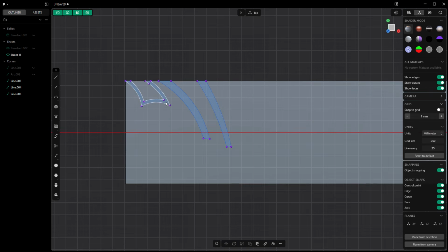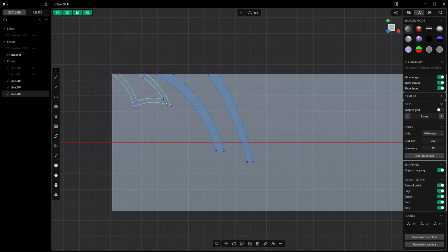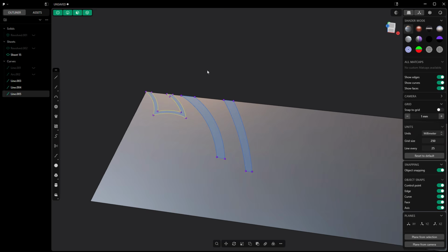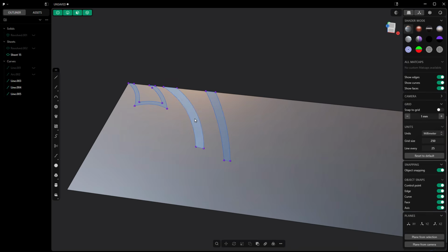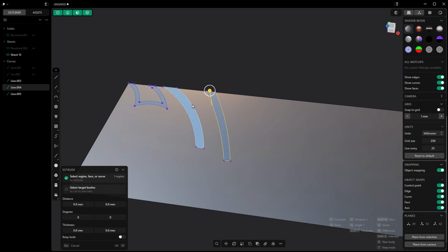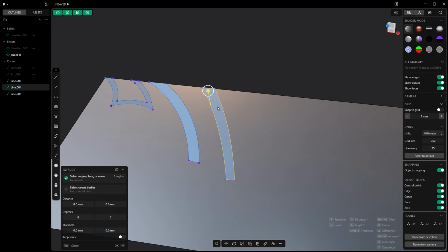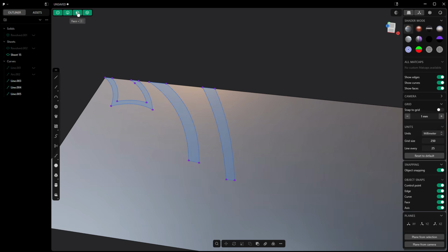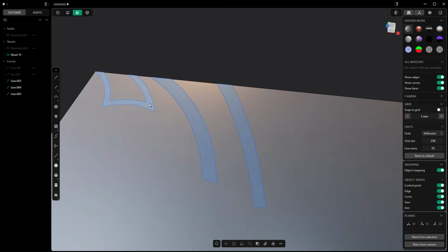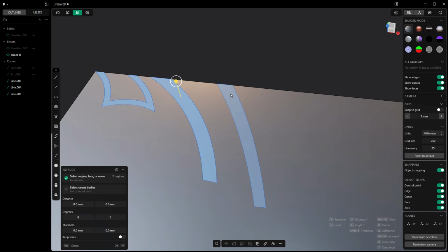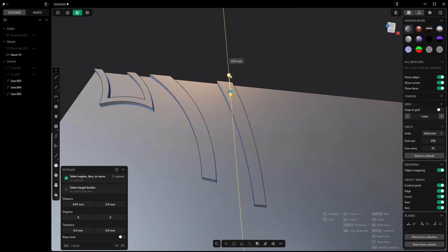But now that we've got this, let's again select profiles. So I'm going to rotate this around. And I want this profile, hold down Shift. Make sure that you're not selecting curves. It can be easier also if you select the face option. It will only let you select the profiles. And then you can begin to pull these up.